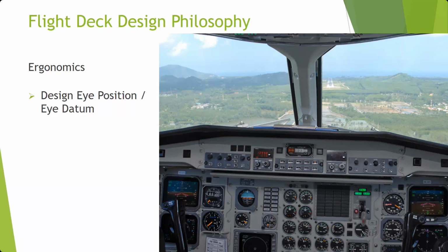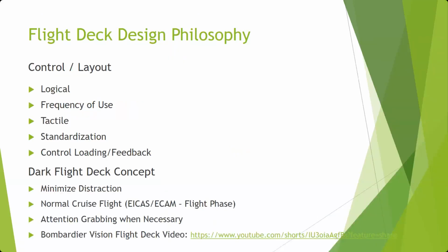You, as a maintainer, are probably going to be working with systems a lot more often. So where are the systems located on a two-crew cockpit? Where are they in the 747 sim we play with? Look up. Okay, most of your system stuff that you'll need to find will be on top. And that's pretty standardized, whether you're in a Boeing or an Airbus or a CRJ or an ERJ.